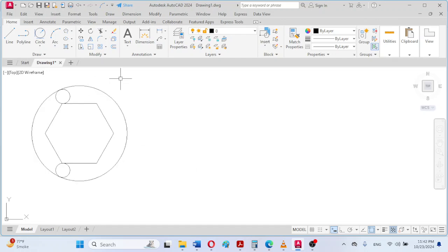Or alternatively we can independently draw this tangent radius circle, the way we had drawn this circle previously, by activating the tangent Osnap. So in this way this jaw has been roughly completed, and we will be trimming in the last stage once the diagram has been completed.